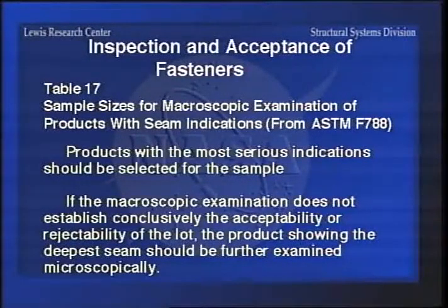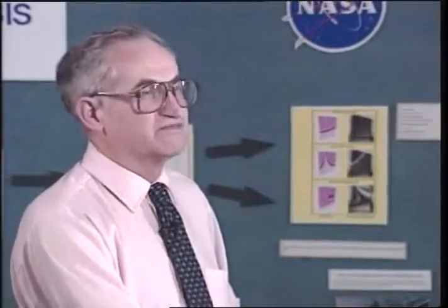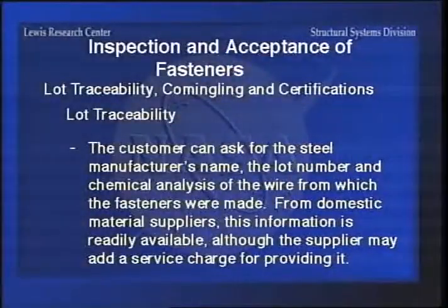There's been a lot of talk on lot traceability and commingling and certifications concerning the Fastener Quality Act, which is also known as Public Law 101-592 as amended by 104-113. One of the things covered in that law is lot traceability of fasteners. The customer can ask for the steel manufacturer's name, the lot number, and the chemical analysis of the wire from which the fasteners were made. And from domestic suppliers, this information is readily available because most companies, when they make